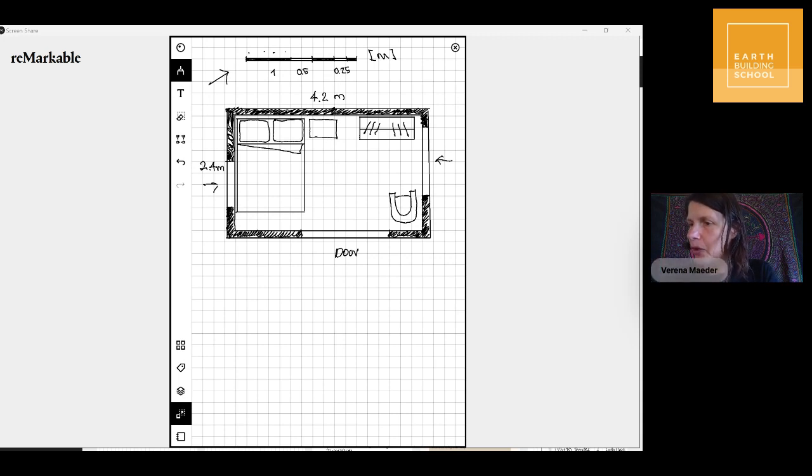So this is the first rough idea of how I would be placing this. And then I'm going to start looking at bracing, and I'm looking at, does placing the windows and doors here actually work in terms of usability of the space. So we're checking the corners first, and again, you need to have a minimum of 900 millimeters, 0.9 meters in your corners.